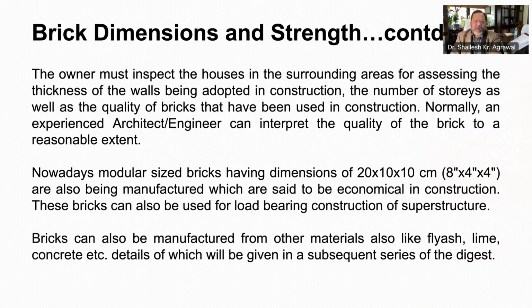The practicing architects and engineers in the region can also help interpret the quality of brick and construction thereon. Nowadays, modular sized bricks are also available, which are of dimension 8 inches by 4 inches by 4 inches, or 200 by 100 by 100 mm, and they are said to be more economical in construction and can be used for load bearing construction.